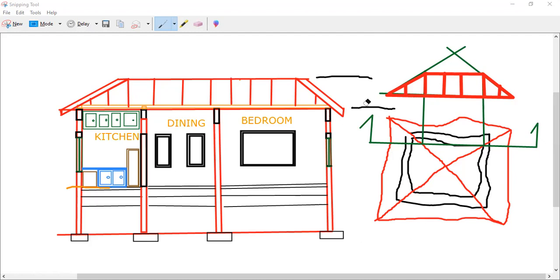So let me delete this one. Use that different color line. To move this to the drawing, you would need to establish your peak points. So what I did, I would match this point here on the roof. I would sketch this from a separate location. You could also just draw a line across, but this is basically how you determine the height and the angle. The angle would be fixed at 30 degrees. You would then copy this, using here as the base point, drag it and drop it right here on the roof to get everything in place. So that's basically how you would deal with that part.